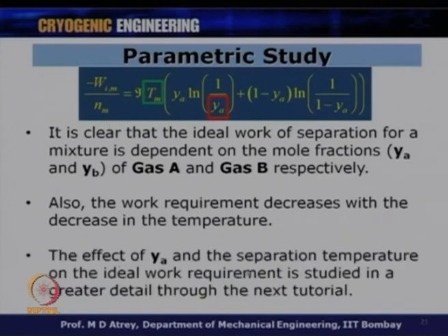The effect of Ya and separation temperature on the ideal work requirement is studied in greater detail in the next tutorial. So, let us study the effect of Ya and Yb, and also the effect of Tm on the work of separation. For this we have taken a separate tutorial to understand the dependency on these parameters, and let us study how Ya, Yb and the temperature of separation change the work of separation for different gases.